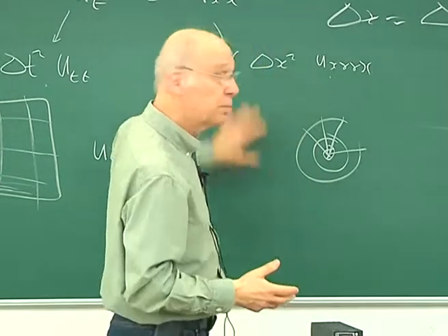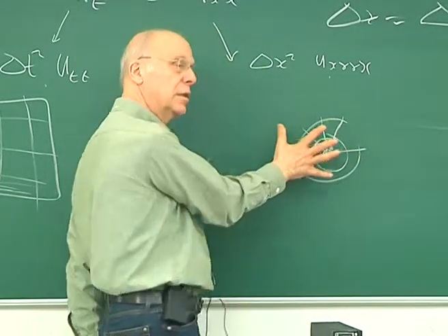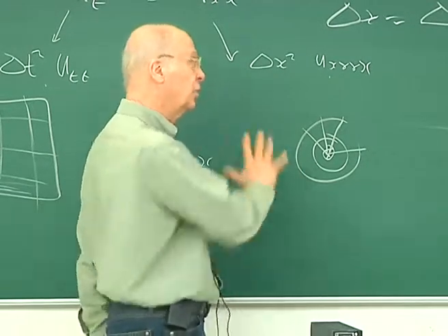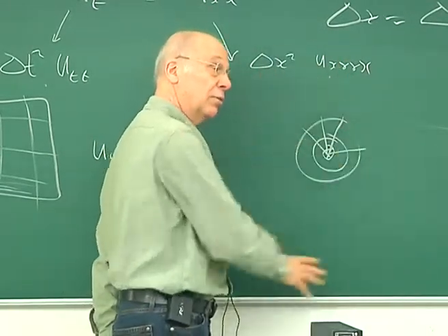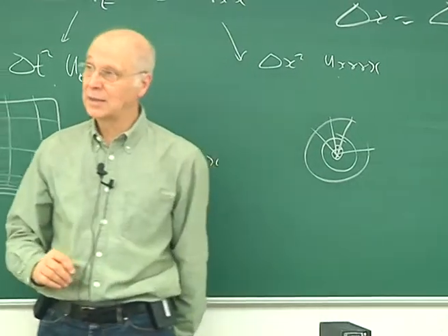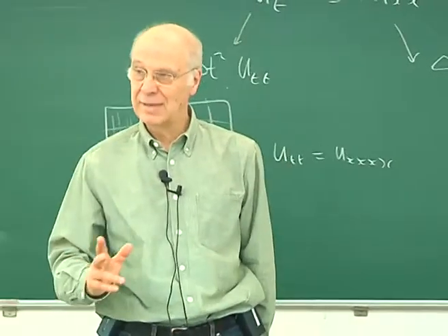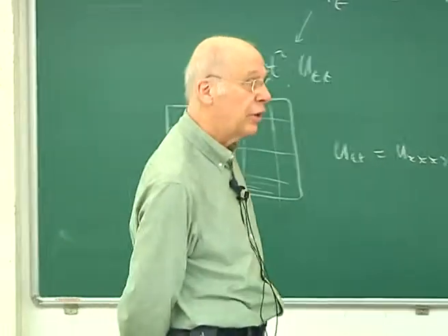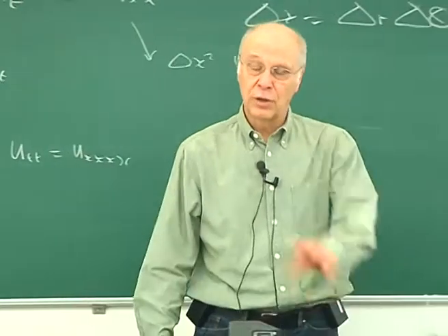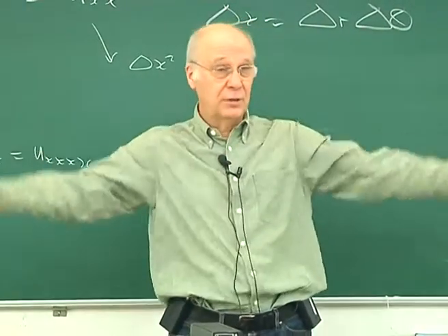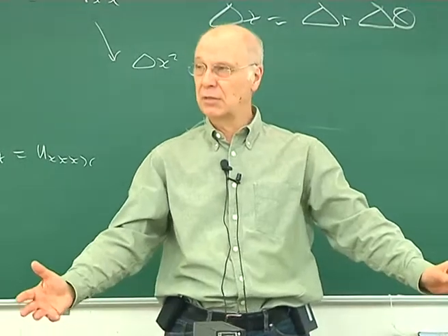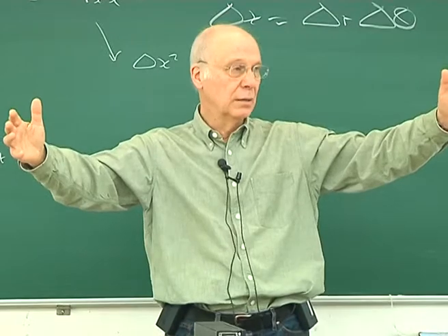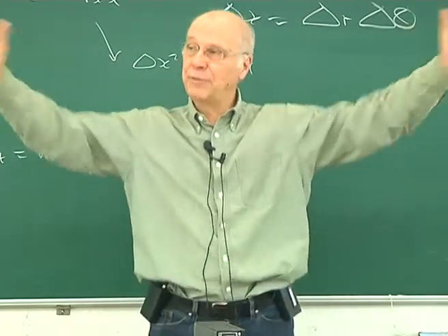So if you want to solve this problem here, you could just slap a Cartesian grid on the middle bit there. Patching it to the polar grid outside is a mess, equals errors. Okay, and then very often we're told to solve flow past the sphere in an infinite domain, and computers don't go very far to infinity. So an infinity ought to be about 3. So how do you bring infinity in?